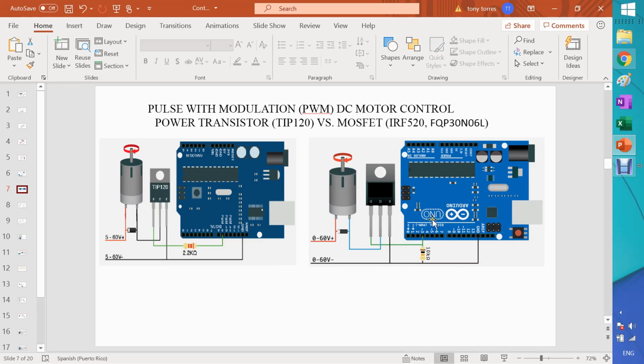However, what I found is if I use any pin, and now it can be any pin, but I set what I call the cycle time. Cycle time, typically for controlling a motor, is 20 milliseconds, and from that 20 milliseconds, depending on what speed I want in the motor, I was able to control from 0 to 20 milliseconds on.